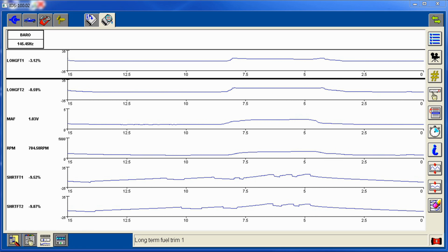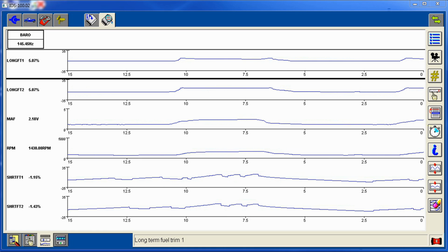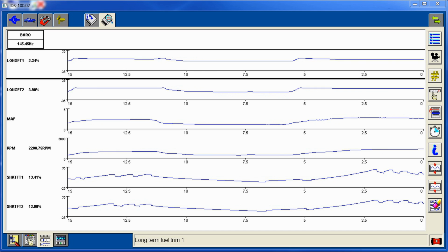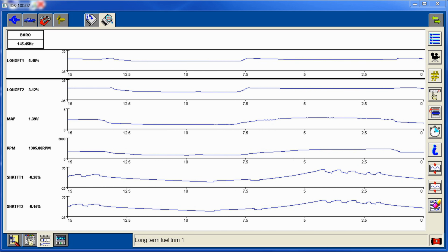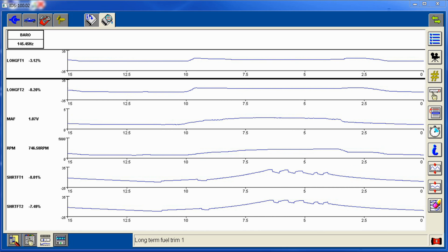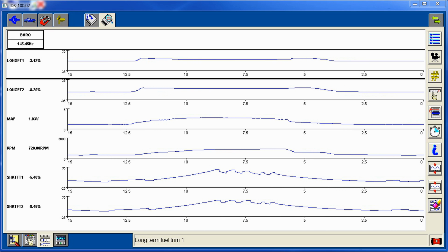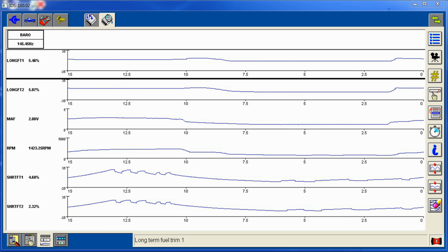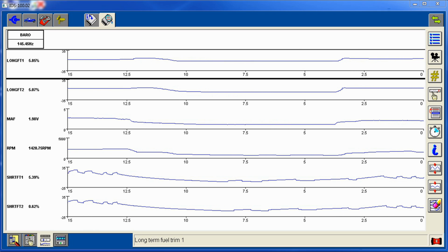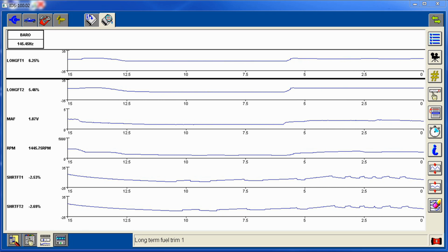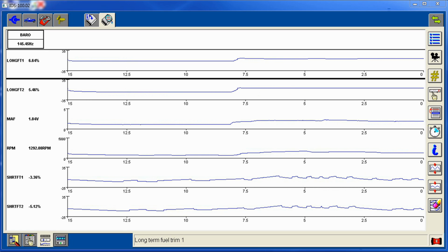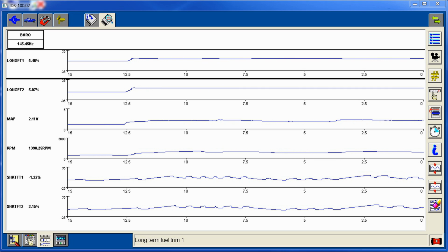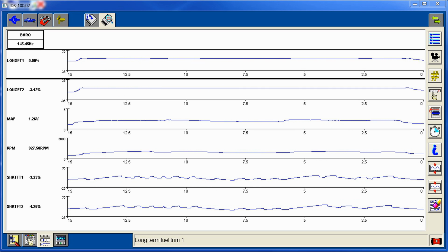And you can see once I start driving and I get a little bit of throttle, that airflow increases across there, and it's not registering. I mean, instantly it reacts and goes lean instantly. And that's another thing. If you're going to have low fuel pressure, you're generally going to not have enough at a wide open throttle position, not mid-throttle. So that's another indication that fuel pressure is fine also, in general.